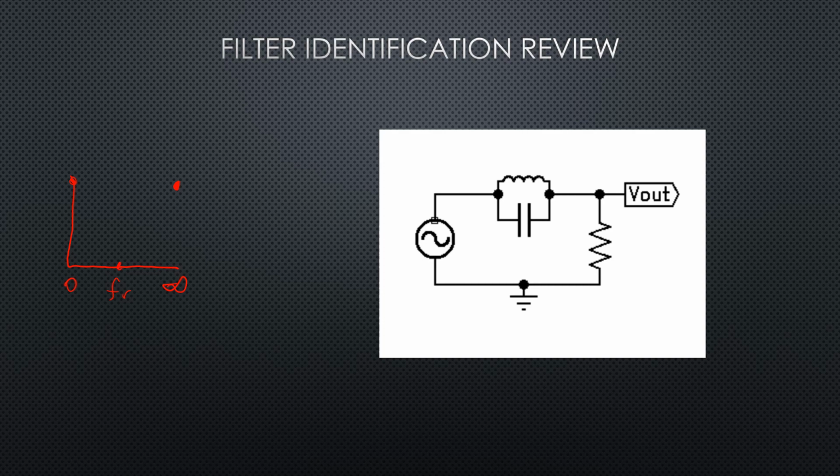So now if we connect this and look at the response curve, we can see that this circuit is a notch or band stop. Now again, if we switch locations and put the tank on the output and the resistor where the tank is, it would invert that response curve and we would have a band pass.